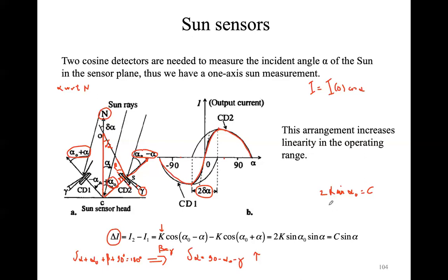You have to be careful indeed that this relationship is only true when you are in this domain, between angle delta alpha and minus delta alpha. To determine delta alpha, we have seen this triangle here. So this is the normal of the sensor S2. And basically, you consider an angle with respect to the plane of the sensor here, a generic angle beta.